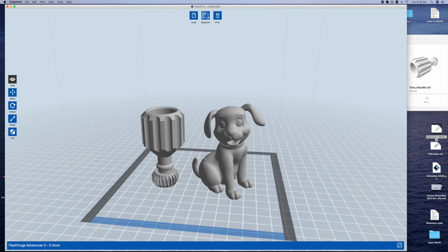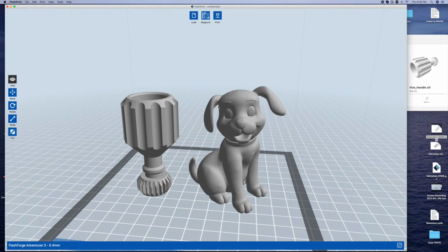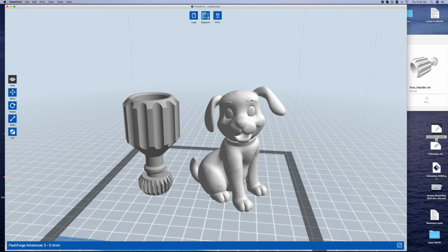First of all, the ears on this dog literally are starting out in the middle of nowhere. The 3D printers go back and forth, building layer by layer, stacking up to the top of the dog here. But at this point, they're going to have to pick up this ear out in the middle of nowhere. Over here is another good example: when an object slants out at over 45 degrees, the filament will sag if there are no supports.